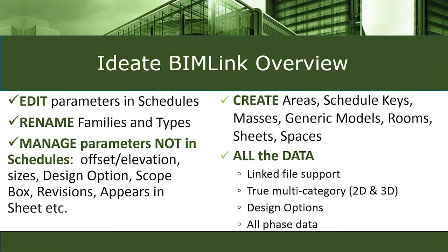I'm sure many of us have had that situation where you're creating a schedule and you know you have some properties, but they're just not available to be checked or put into the schedule. Certainly things like the wall height, offset elevation, sometimes the design option information, scope box, revision information. So we're trying to expose all of that to give you the ability to modify it in Excel.